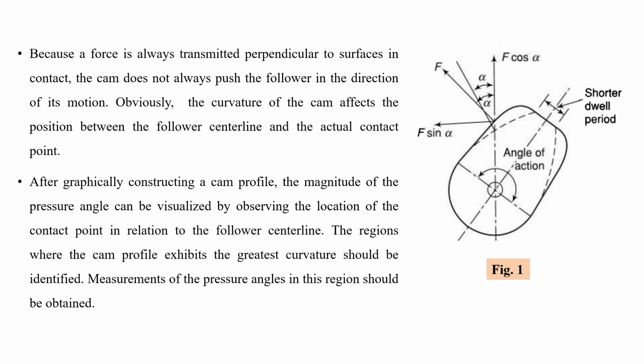After graphically constructing a cam profile, the magnitude of the pressure angle can be visualized by observing the location of the contact point in relation to the follower center line. The regions where the cam profile exhibits the greatest curvature should be identified. Measurements of the pressure angles in this region should be obtained.